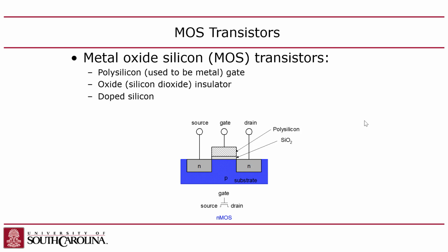That makes sense? Now you might say, well, what happens to the boron though? I mean, do you end up with boron and arsenic in there? I think so. I don't know exactly how it works, but somehow you can reverse the type of the silicon by adding the opposite thing that had been previously doped with, right? I think what ends up happening is if you have more arsenic in there than boron, then it becomes n-type, right? But it only happens in these islands, and this is where photolithography comes in.